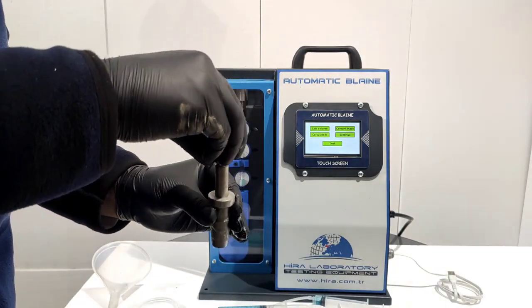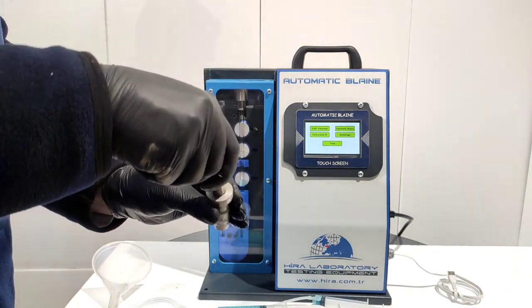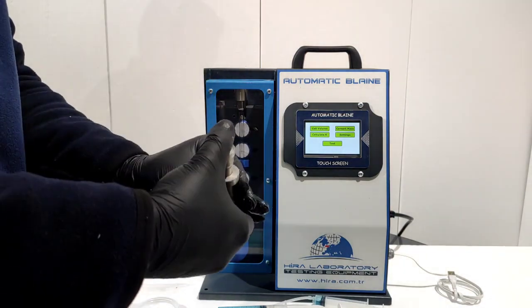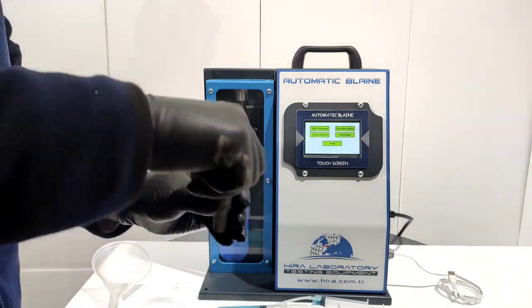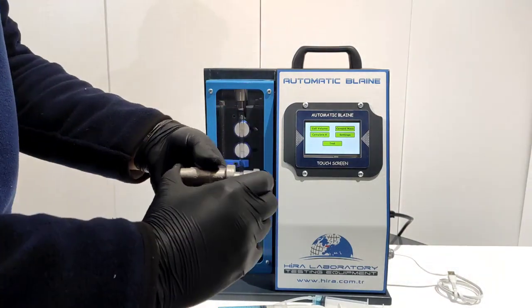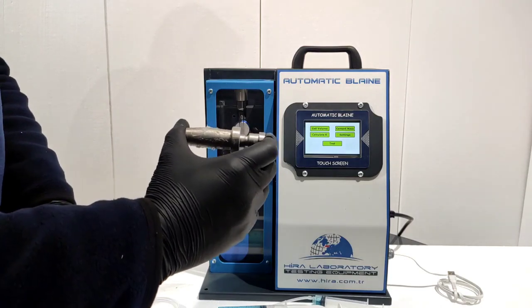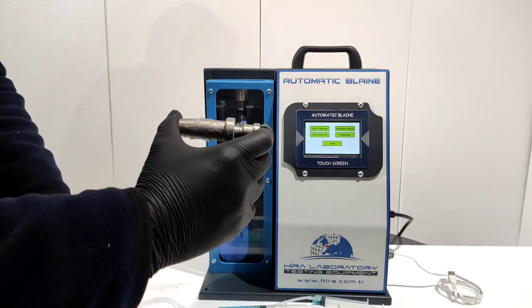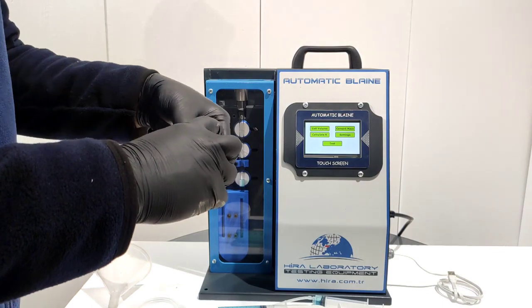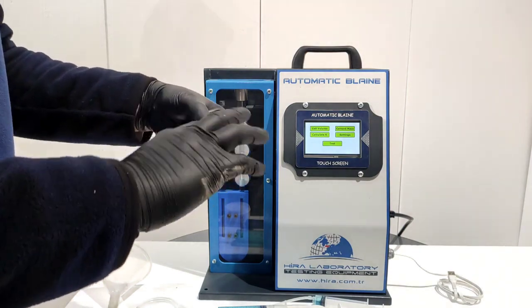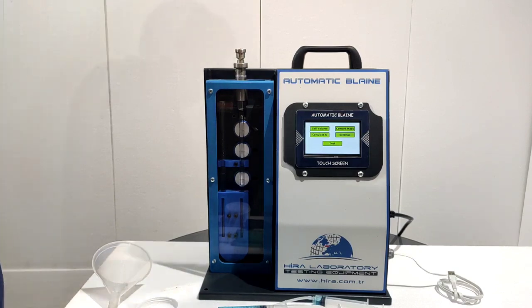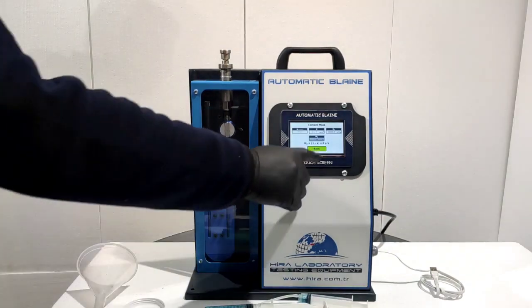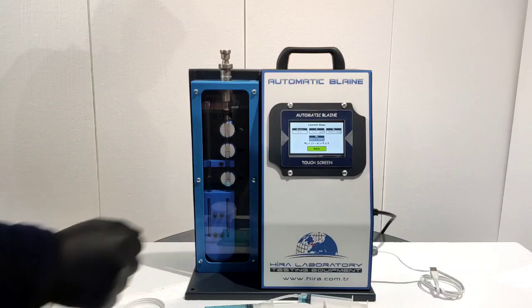To compress the cement in the cell, press the plunger lightly but firmly onto the seat with the bottom face in contact with the top edge of the cell. Then slowly lift the plunger about 5 mm by turning 90 degrees and press it back onto the cell. The cell is now compressed. Slowly retract the plunger without disturbing the sample cell. Place the lightly oiled cell into the U manometer tube.